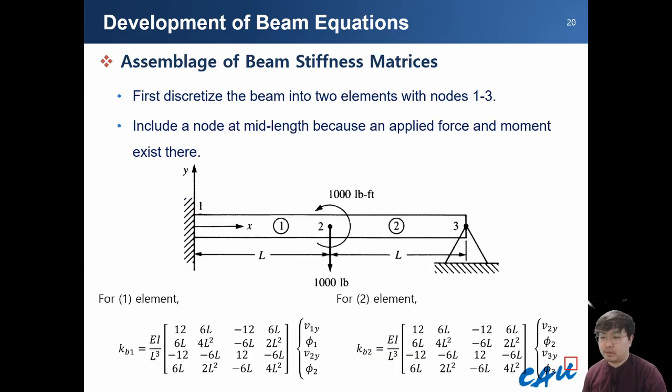So, I stopped the lecture today here. Up to this lecture, we obtained the relationship between displacement, transverse momentum, rotation, and moment. So we finally obtained the local stiffness matrix equation for the beam element. Using the beam stiffness matrices, we are going to assemble and analyze some solid structures. So this is a basic example.